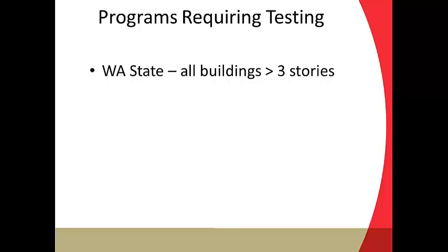If they are in the Seattle area, they are allowing buildings to pass as long as, if it fails the test, you make a good faith effort to air seal it. They're letting it pass without achieving that 0.4. They're trying to make this an achievable standard when they're starting out, and they've had pretty good successes out there with testing large buildings.